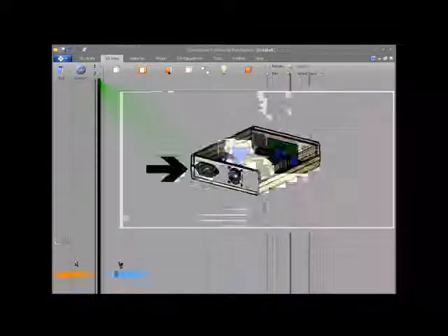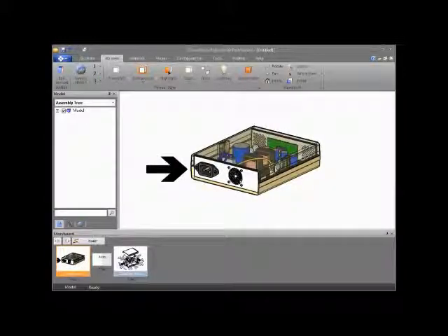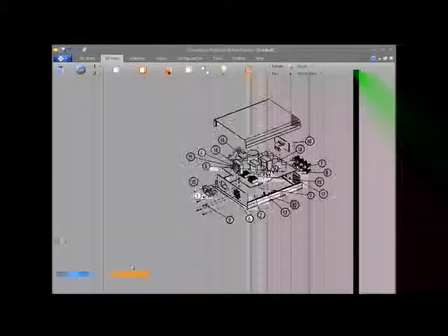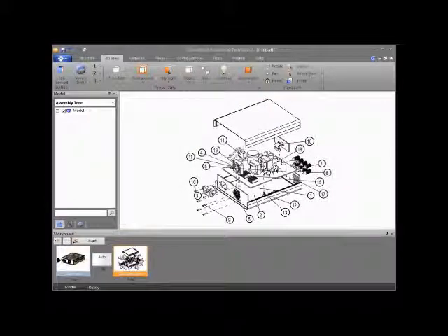And so we now have two illustrations. We have this one which we created, which has an arrow overlay, and this one, which is just a ballooning of our exploded view. Now you could go through and generate any number of illustrations, and they will populate the storyboard bucket down here, which is used for grouping them. And once you have generated your illustrations, the next step would be to publish those.